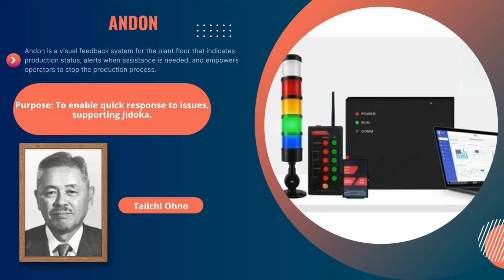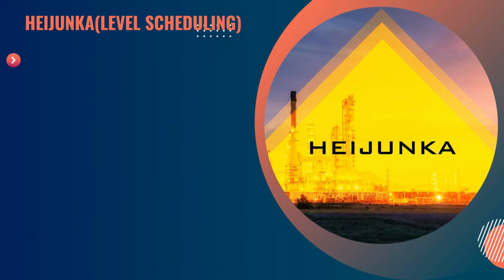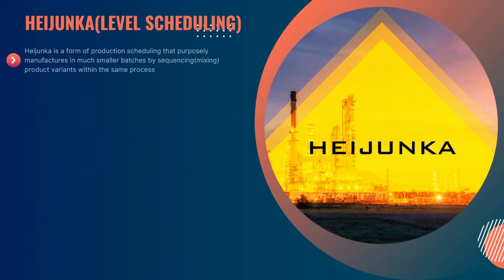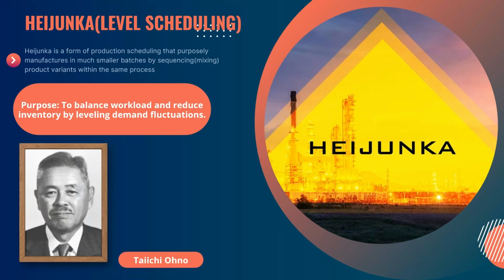Now let's go to the next slide and understand about the Heijunka principle. The Heijunka principle, also known as level scheduling, is a form of production scheduling that purposely manufactures in much smaller batches by sequencing product variants within the same process. What's the purpose of it? To balance workload and reduce inventory by leveling demand fluctuation. Who gave this concept? Again, Taichi Ono.